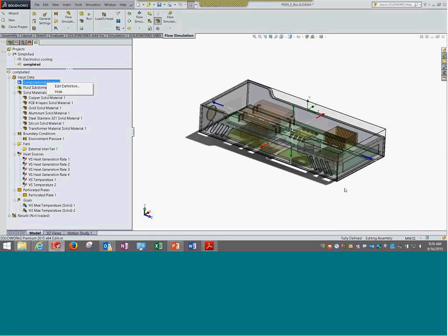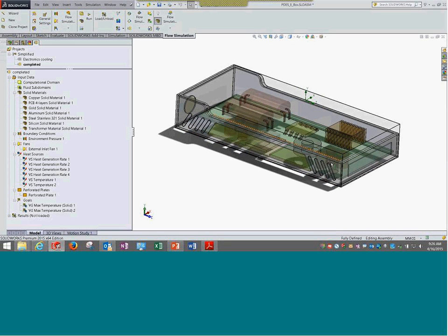So it should create this particular closed domain and show you the boundaries of the internal domain. We may not go into detail, but we are actually creating these lids as well before we start this analysis. These can be created using the lids option in Flow, or they can be created in SolidWorks CAD separately. So all lids have been created in this simplified configuration.